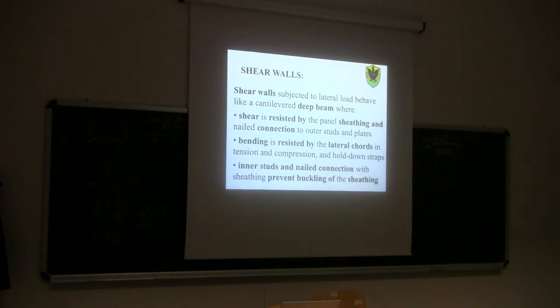Why is it the same? It's what I learned as the reciprocity of the shear stresses, or the fact that the shear tensor is symmetric with respect to the diagonal.